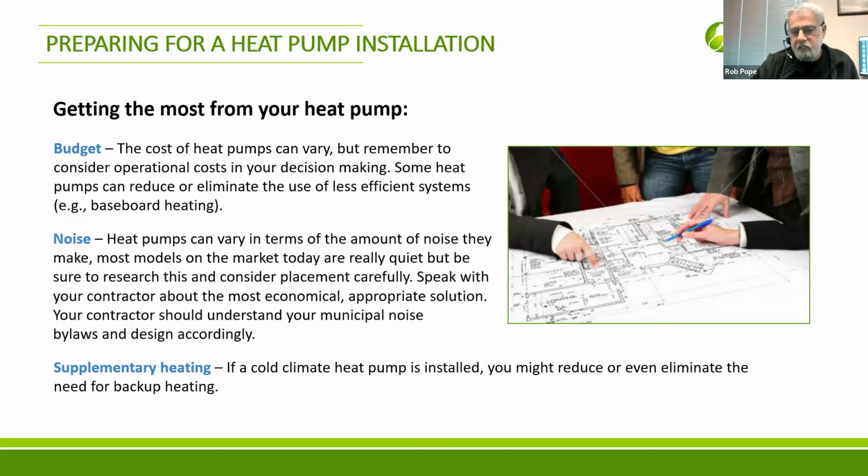Noise is a big thing. It's not just the outdoor unit, it's the indoor unit as well. Obviously, an inexpensive single stage heat pump is not going to cost much at all. It'll be easy on a budget, but it'll be noisy as hell. Different manufacturers have different grades of product for different budgets, and obviously one of the things that gets compromised in less expensive systems is noise. So it's critical to check those dB ratings and make sure that it's going to be acceptable.